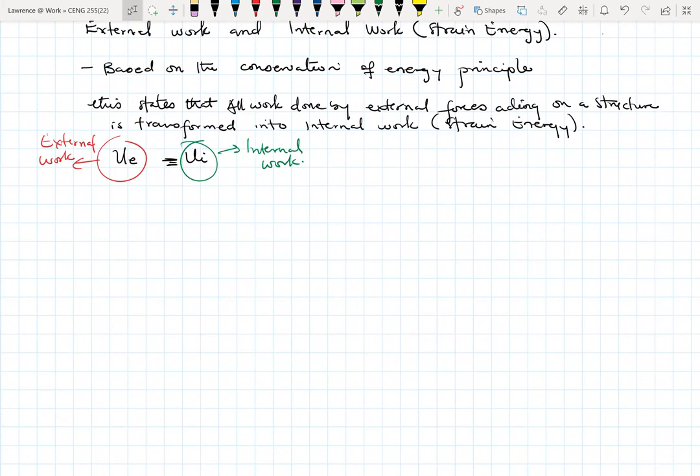But even before we formulate the equations, this is usually true if you're looking at the elastic region. The elastic region is a region whereby when you apply some load to a structure, there's some deformation. Let's say you have a beam, and you apply a load P to this beam. At some point, the beam will deflect by delta. If we take the load away, we are assuming that the beam would return to its original, undeformed position. Once that happens, it means that we are within the elastic region, and we've not exceeded the elastic limits.